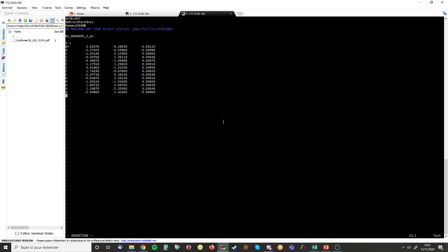If you don't have a blank line, it will be stuck waiting for a new line because it didn't get the order to say that the geometry is done, and it is waiting for an interactive approach where you can put atoms interactively, so it will crash. So leave a blank line after the coordinates.